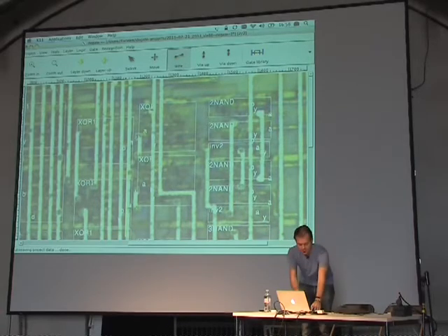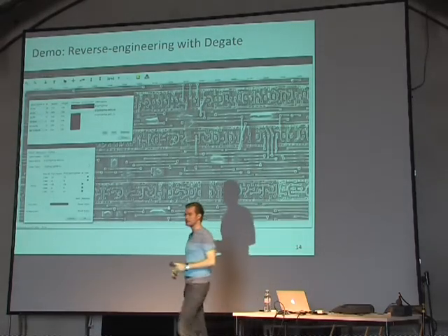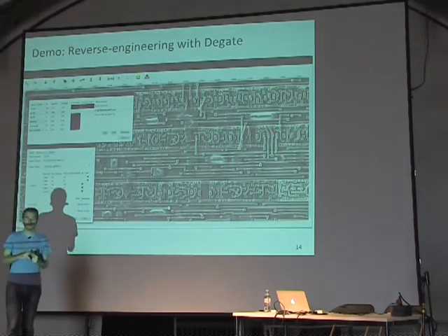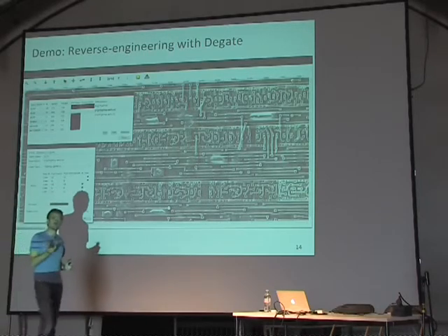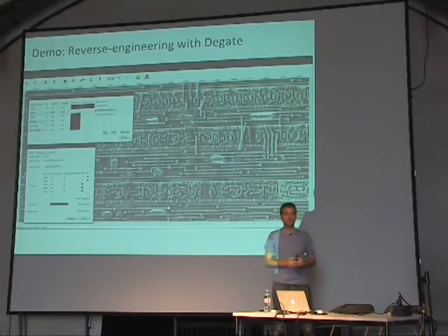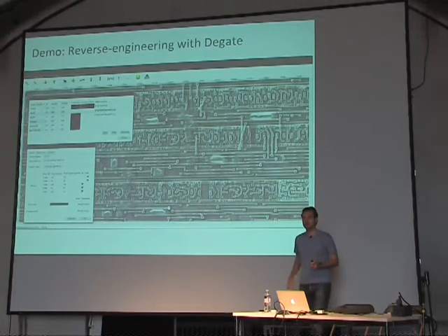The tool can also notify you of potential errors. What never happens in silicon, for instance, is that two outputs are connected to each other, of course, they would be fighting, or that there are inputs of gates not connected to anything. So there are some rules to what the circuit has to look like, and the tool will notify you of all the rule violations. So it does the first debug run, basically, for you. So eventually, you reach a Verilog or VHDL representation of whatever is represented in the pictures you took.